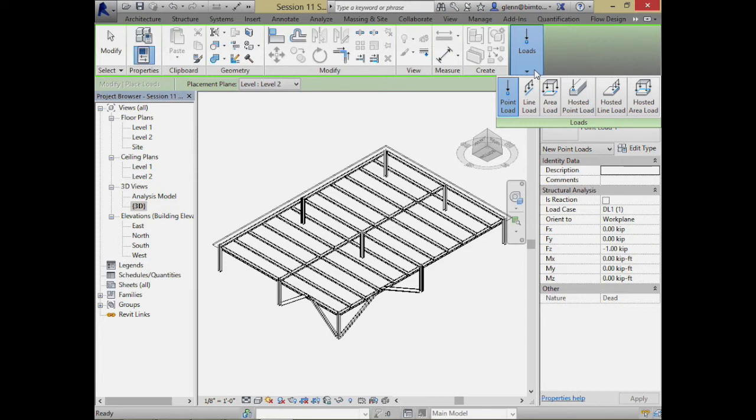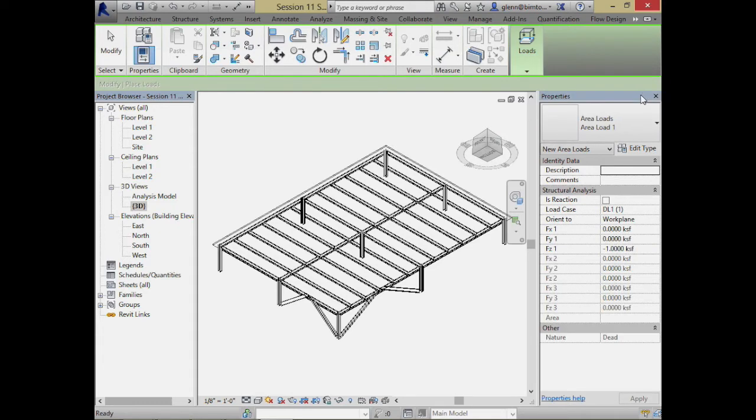So what I'm going to do is put a load on the floor by choosing the floor as opposed to explicitly choosing the area. So I'll say there's a live load. Oh, we get to choose loads. Loads all have a category. Right in here is where you can say which load case it is. So this is the dead load case. We should also put a live load on there. So for our dead load, do you have an idea for a concrete floor, how many pounds per square foot that is, with some steel underneath it? Any sense? Again, I don't know offhand, so you can guess.